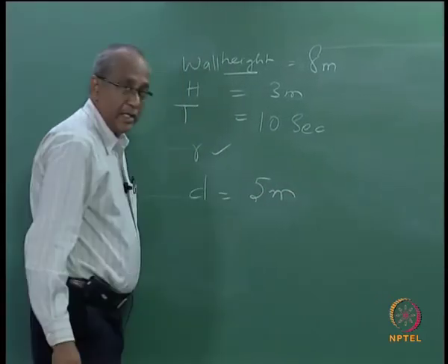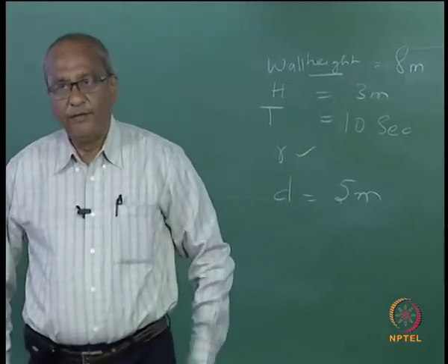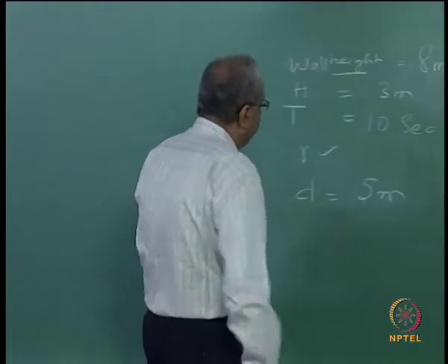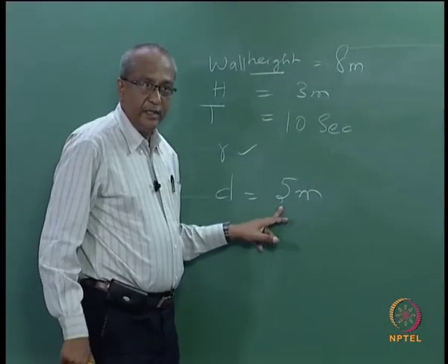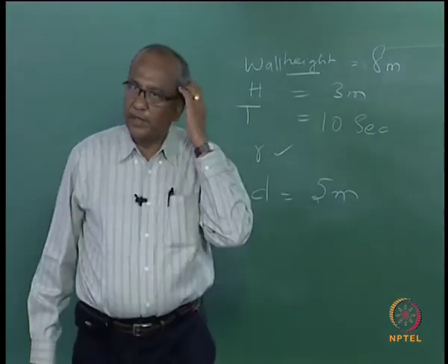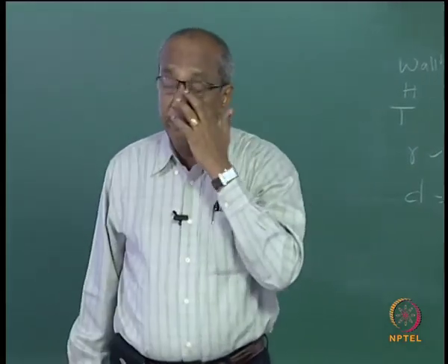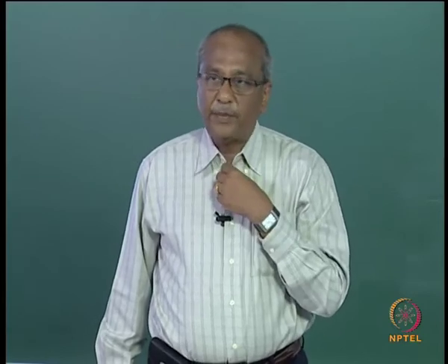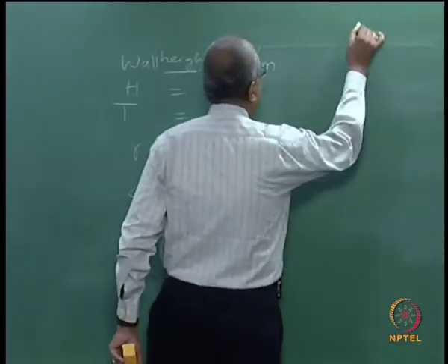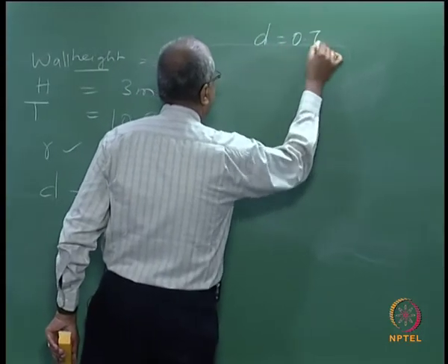As per your statement the depth should be 5 meters, and a wave height of 3 meters can sustain in 5 meters, because the maximum breaking wave height can be 3.9 meters because of this condition, okay.